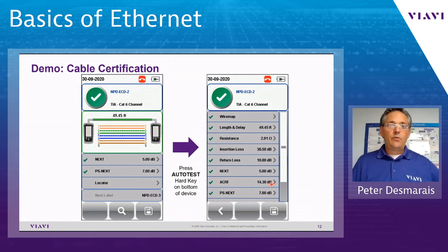All right, so we mentioned earlier that a cable certifier does about 13 different tests on a cable. Just wanted to show you, this is the screenshot off of a Viavi Certifier 40G. This is our cable certification tool. In this case, we've run a test. I hit the start test button. In about 10 seconds, the test will complete. It'll show you if it passed or failed.